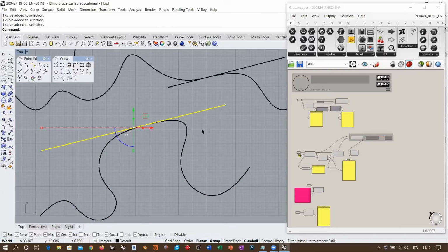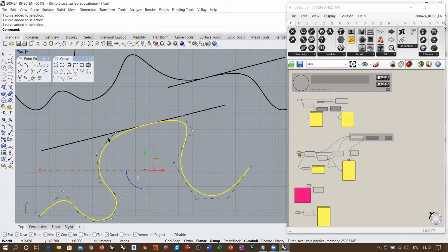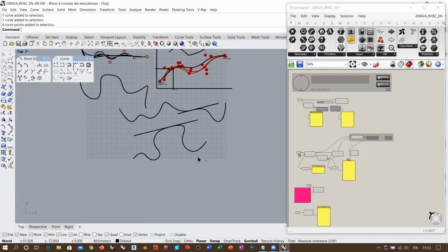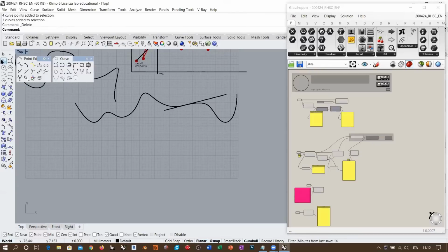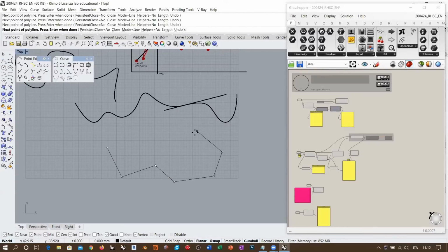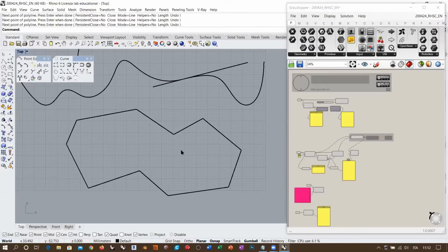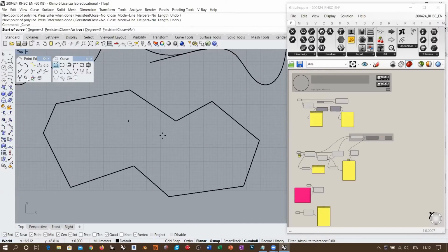Okay, so we can define, for example, the tangency of one NURBS curve to a specific line, and we are seeing that this happens by aligning three control points. So this is already something that has some use for us. For example, if I have a region in our plane, but it can also be a 3D region, and we want to draw an organic shape inside this region without exiting it, then we must take into account this second rule that we just saw. By aligning three control points, we become tangent to a specific line.